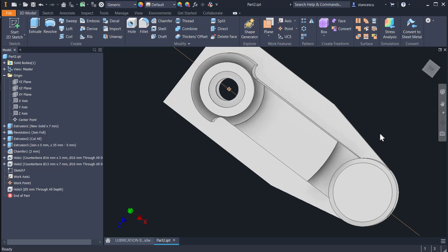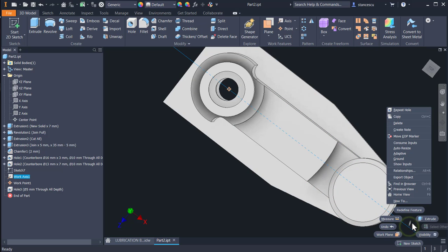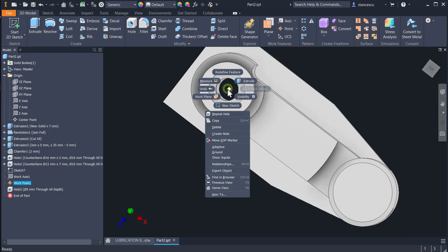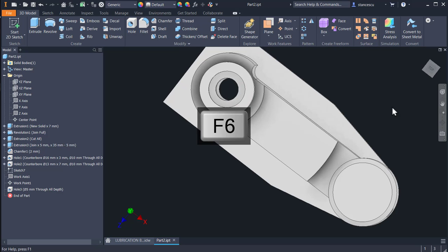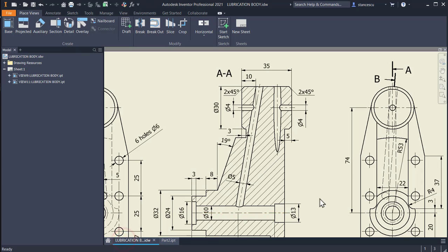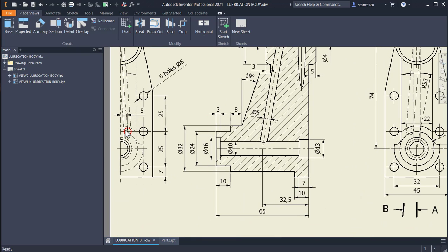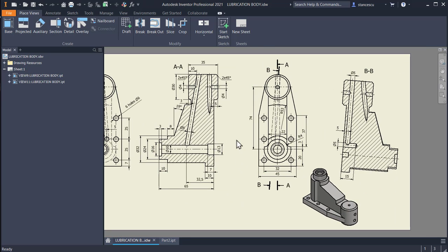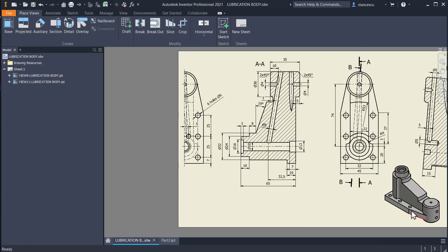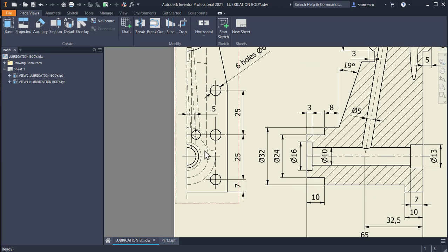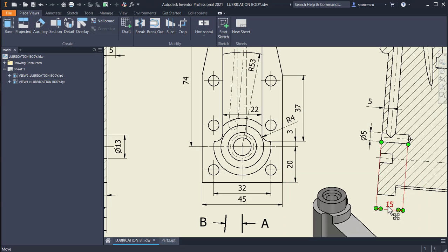This is placed in a diametral plane. I don't want to see the axis, I don't want to see the point. Good. Now the other. What is its definition? Its definition is to start from this hole, so we have to create that hole, which is on the back, on the bottom face, placed at 7 plus 25 on this direction and 5 from the mid-plane. We create this hole, which is diameter of 5 and depth of 15.